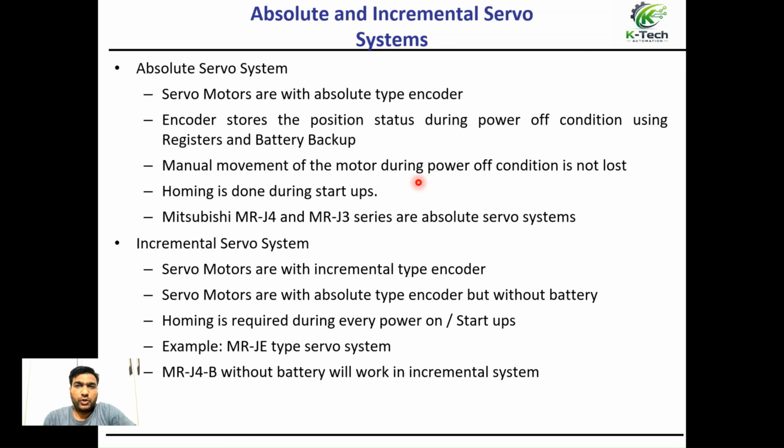Manual movement of the motor during the power off condition is not lost. Homing is done during the startups. Okay, one time, at commissioning time, you need to do homing, otherwise it is not required.